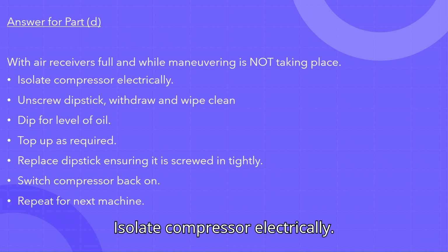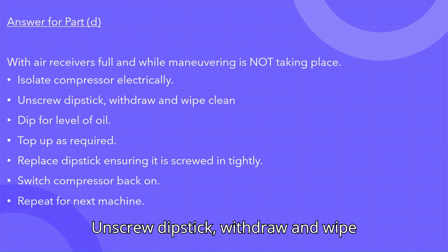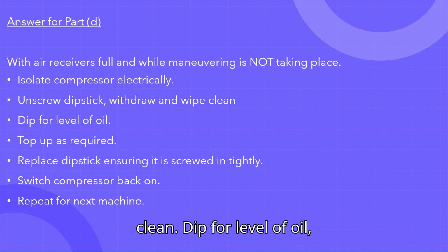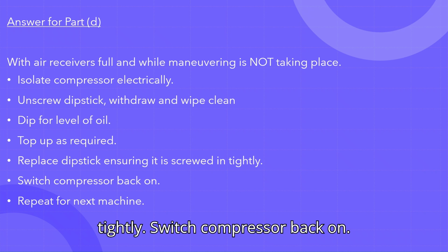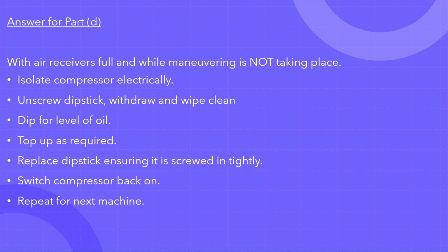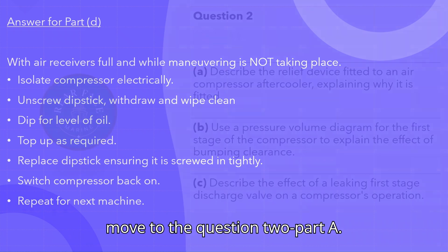Isolate compressor electrically. Unscrew dipstick, withdraw and wipe clean. Dip for level of oil. Top up as required. Replace dipstick ensuring it is screwed in tightly. Switch compressor back on. Repeat for next machine. Let's move to question 2.